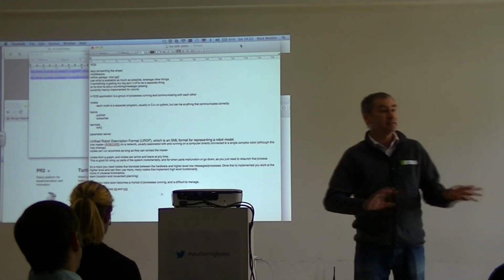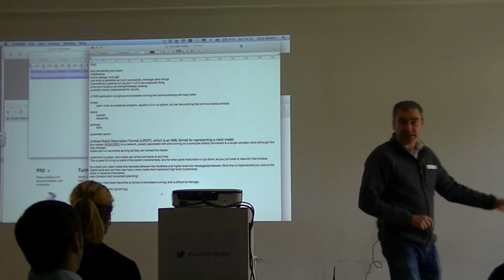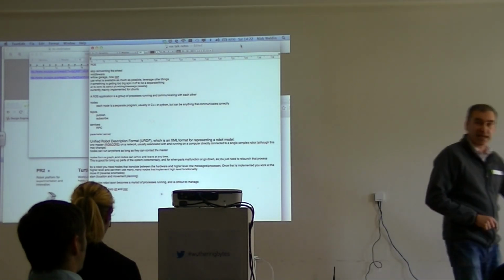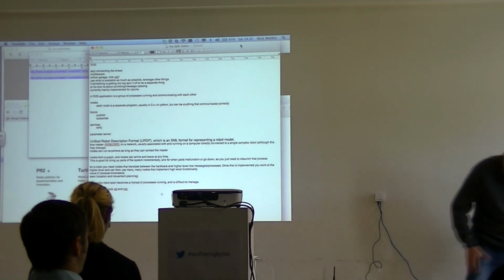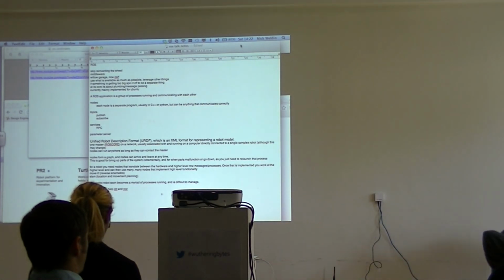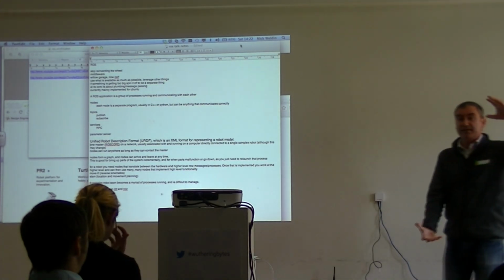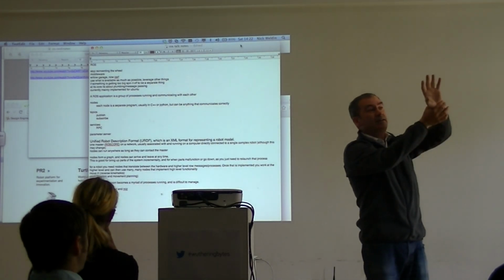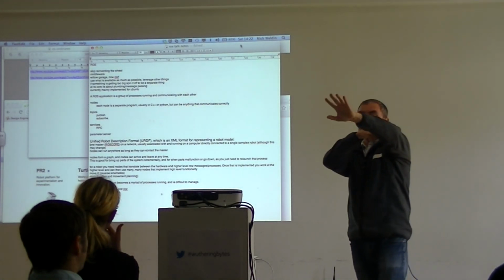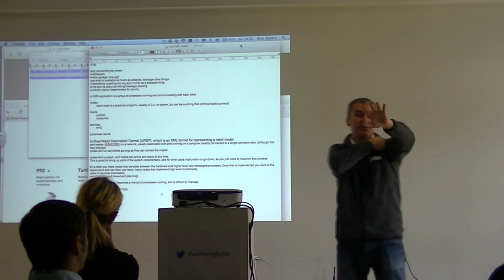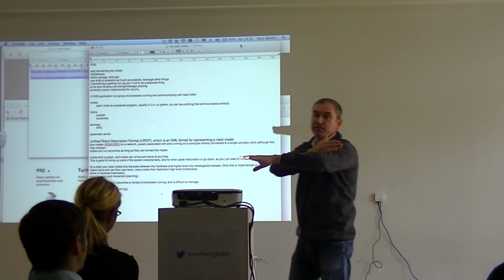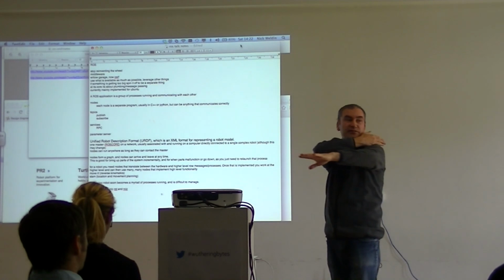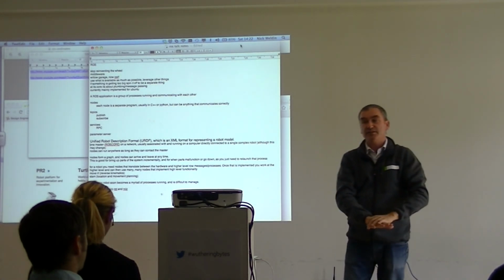It's about message passing. It's about talking to the base and telling the base to move somewhere, the base giving you information back about where it is, talking to something like a Kinect and getting messages from that, and joining them together. So what you need to know is what's the difference between where the wheels are and where the camera is that's recording stuff. Or if you've got a multi-joint arm, when this is here, what do I need to do to control this point? What do I need to control this point? So you end up doing lots of things called transforms, where you're calculating what's the orientation of this, how is it related to that, how is it related to that, and you have something that's defined as the base.